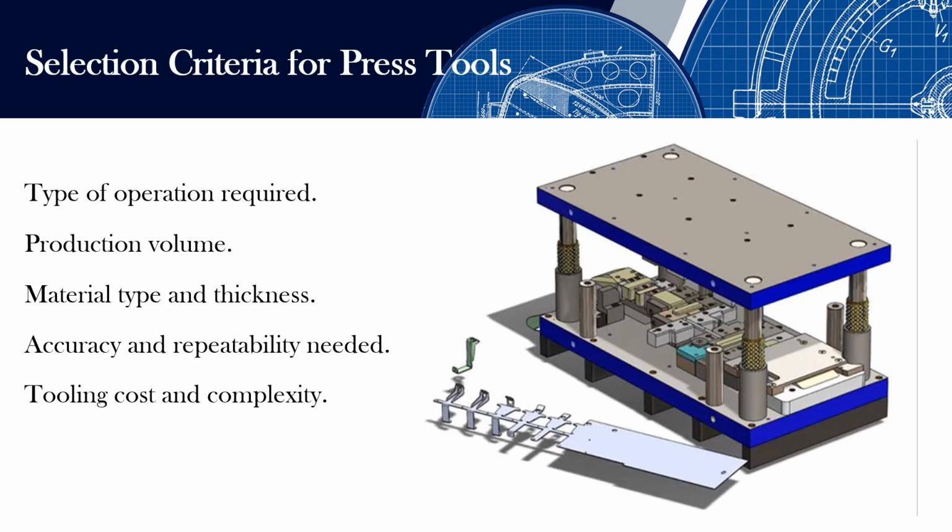Selection criteria for press tools: type of operation required, production volume, material type and thickness, accuracy and repeatability needed, tooling cost and complexity.